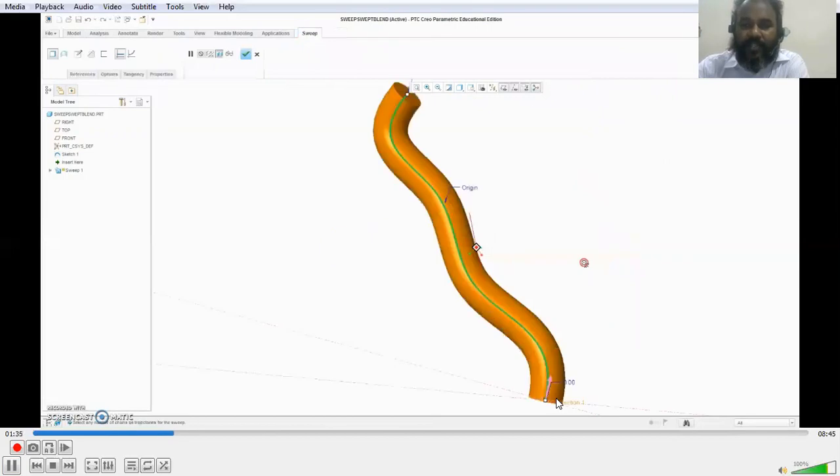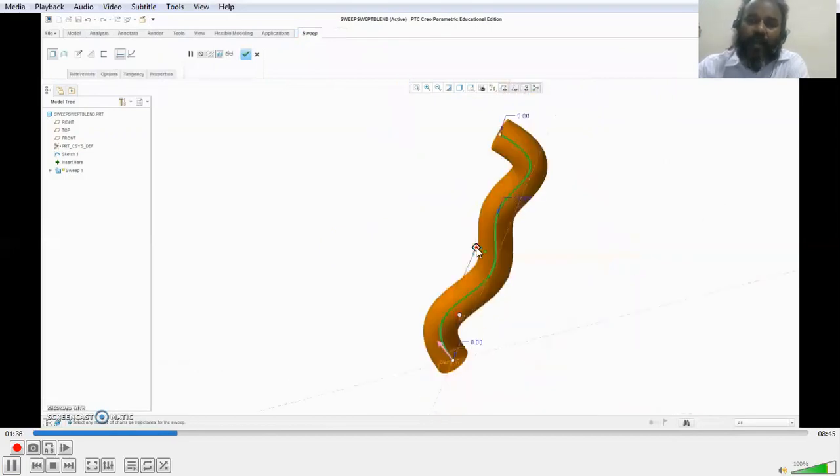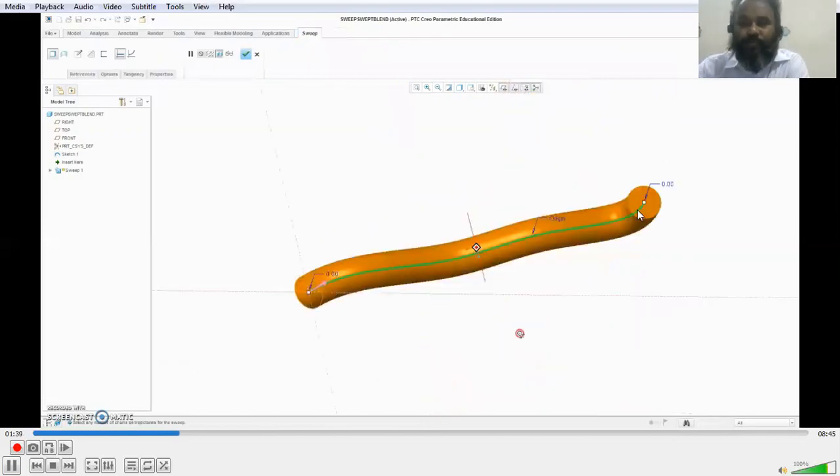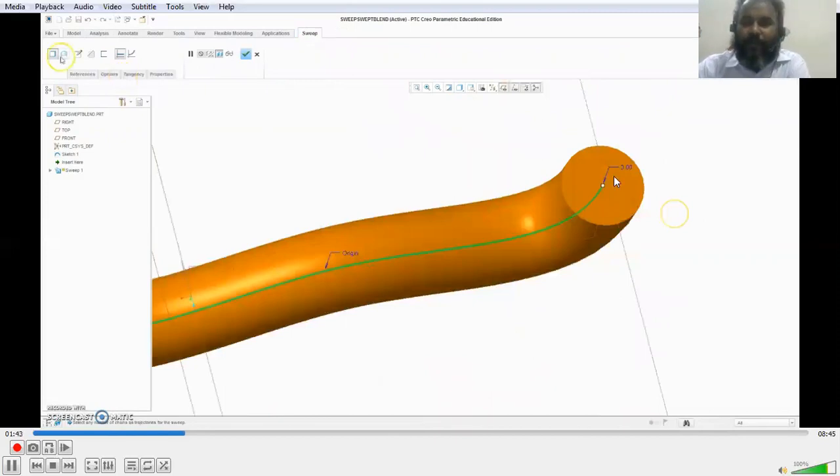So once that is done, you get the spline, which is expanded into the swept part, a complete swept part is obtained. So by choosing the option between this and this, for this I get a solid, here I get a shell, say an outer shell. The surface alone is swept. The inner part will be absent here. So you can create a pipeline of normal diameter, any defined diameter of any particular shape, also shape and size.